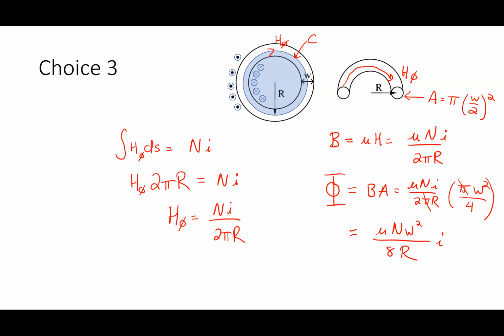Now, let's say I wanted to get the inductance of this whole thing. How do I get the inductance of the whole thing? There was one step before I got to the inductance: flux linkage. This is the flux going through one turn, then another turn, then another turn.